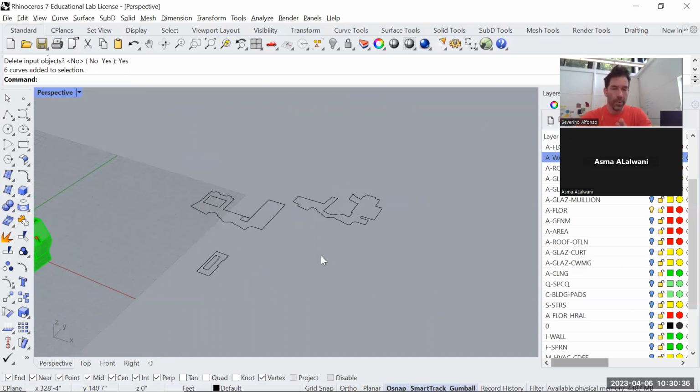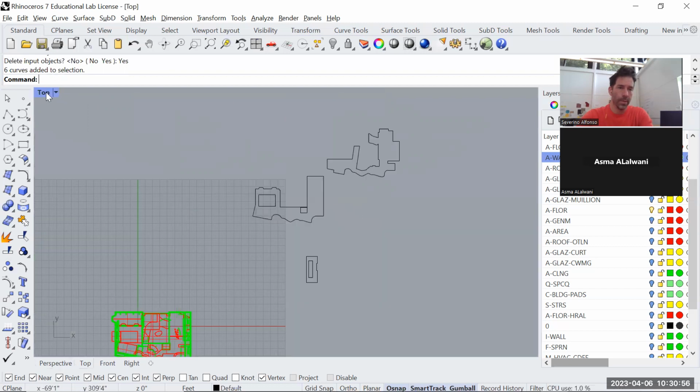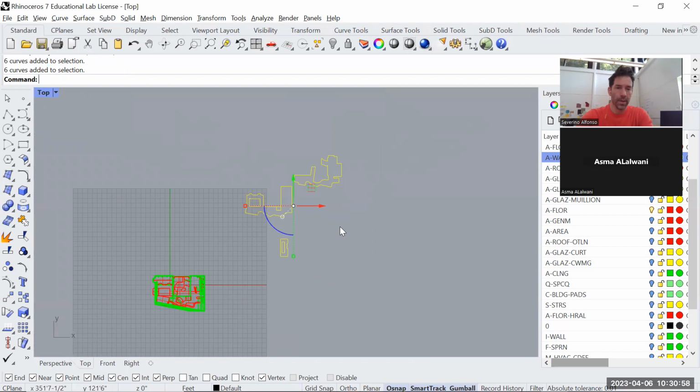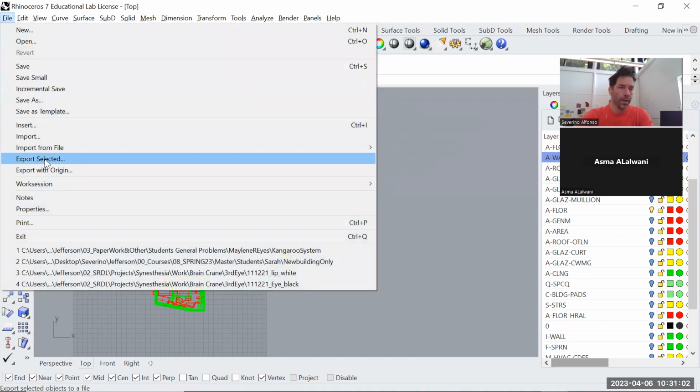So, okay, there are many options depending on how you're going to laser cut. Ideally, it is either Rhino or Illustrator. You can do a PDF as well, but to do a PDF, you probably do it from AutoCAD. So I think AutoCAD is one of the most useful ones, but you can do it in any of those vector-based programs. Ideally, you go to top view, I double click there, double click here. You're going to select the line drawings, and you're going to say Export Selected.